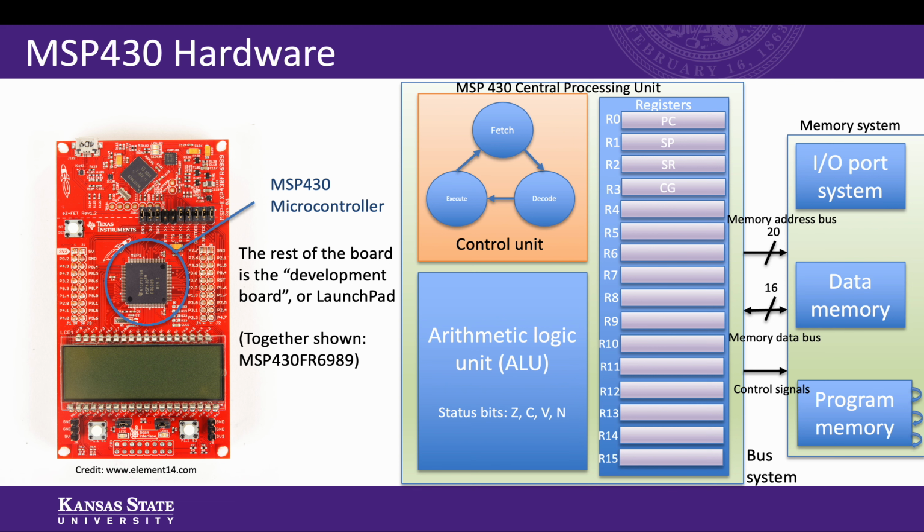The CPU uses the address bus to access the memory locations, so the address bus points from CPU to memory. The data, on the other hand, moves both ways depending on if the CPU is to read or to write data to and from memory. I said technically the device has 20 memory address bus lines. However, usually when we address, we will use 16 address lines, and the other 4 will be 0. I'll elaborate on that in just a little bit.